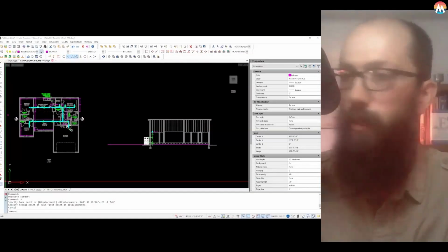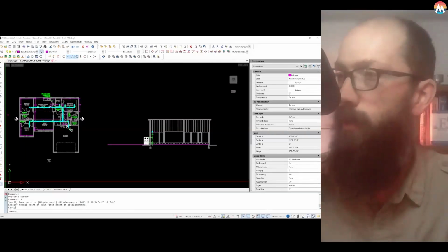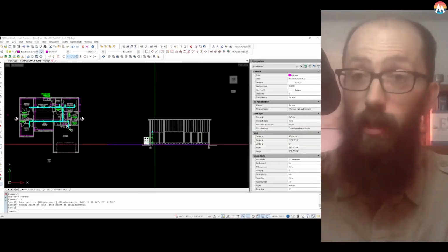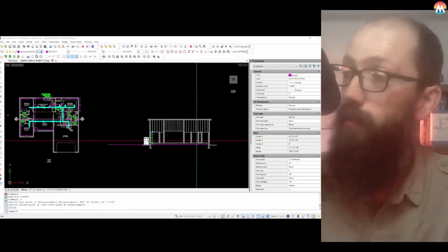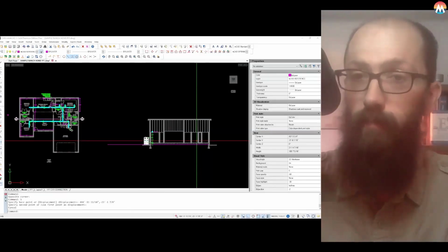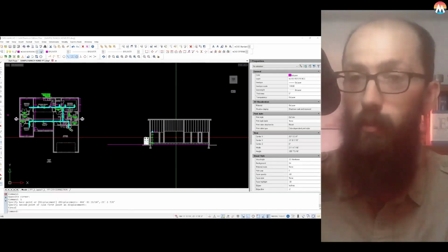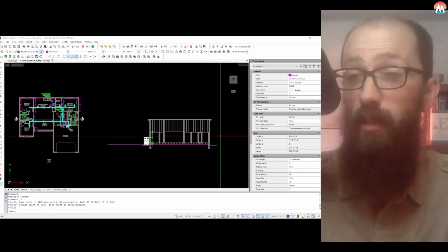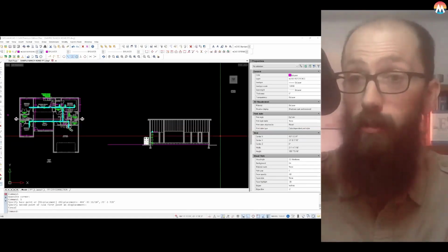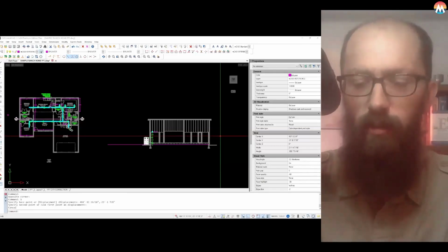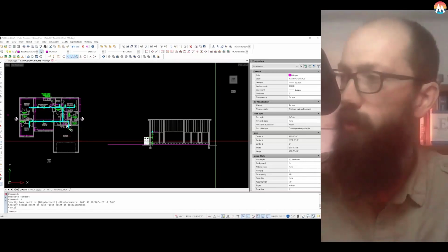All right, we need to do a little bit of work with our cross section here. Now 13D does not require a cross section, but if we have one, we provide it. Some plans examiners can't wrap their heads around the idea. We've actually been required to have one when none was provided by the architect, and we had to create one ourselves. And that's really unusual, and the sprinkler contractor should not be required to create a cross section. That's for a 13D system for a house. That's beyond the scope of their abilities normally.